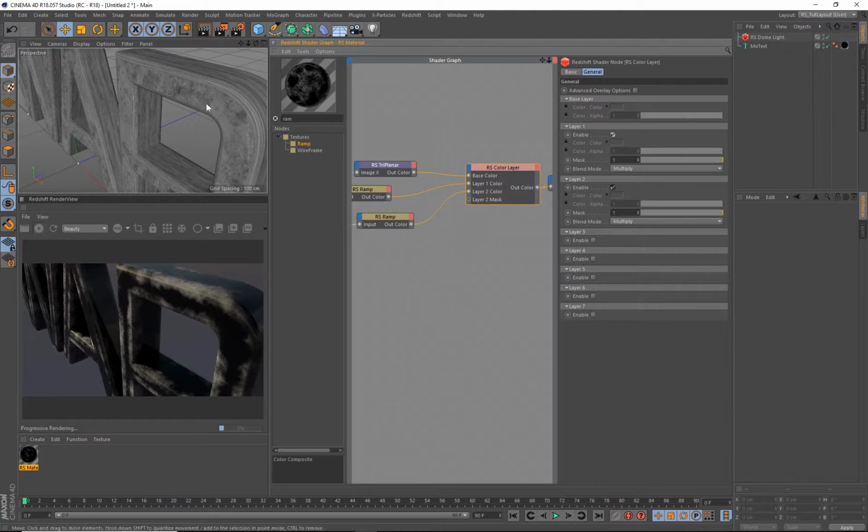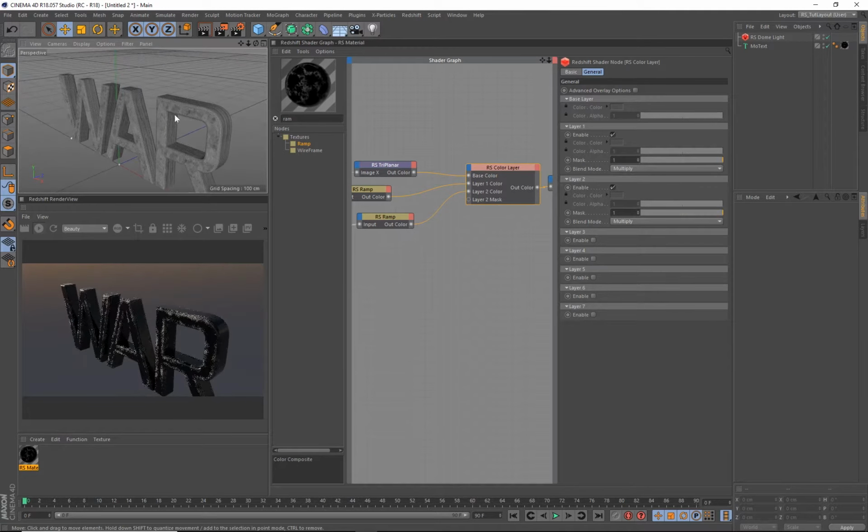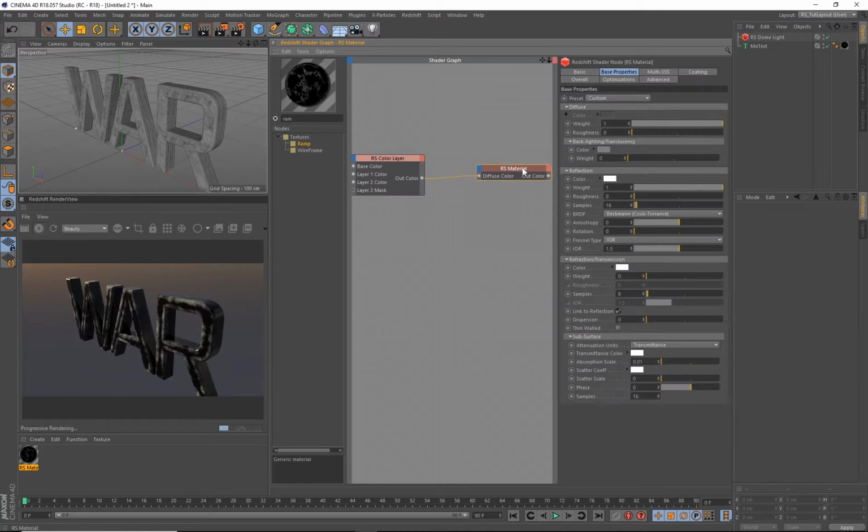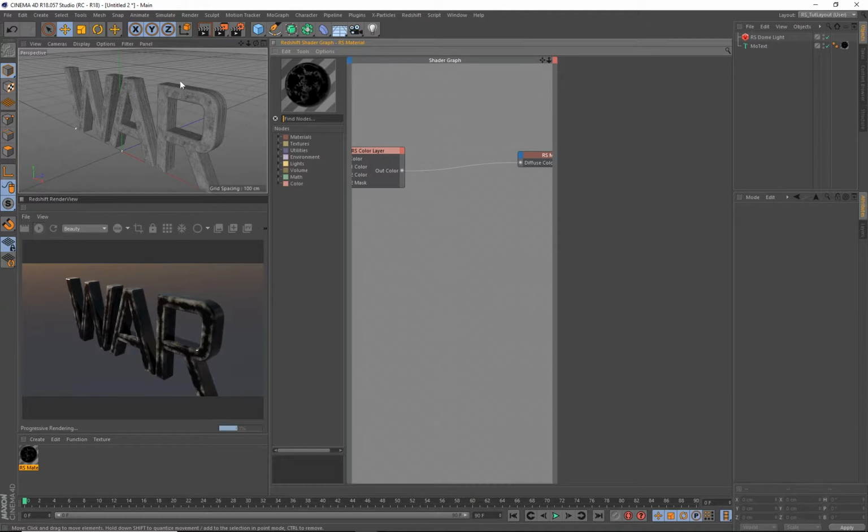At this point, a good question to ask is what map are we making here? If you take a look at it, one could argue that if we're trying to create some worn metal texture or worn metal material, this black and white map that we're making could arguably be used for a reflection weight. But since the current outsides are white and the faces are black, what that's going to do for reflection weight is have the edges be exposed and show reflection, where the faces will have the reflection turned totally off, and that is the opposite of what we want.